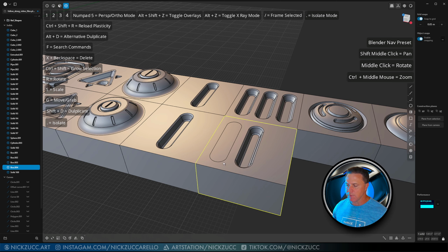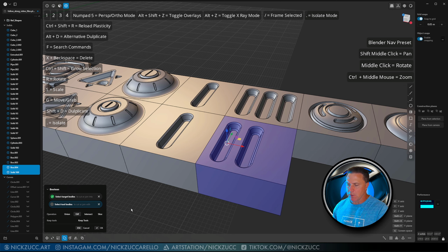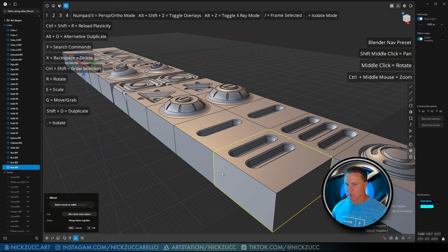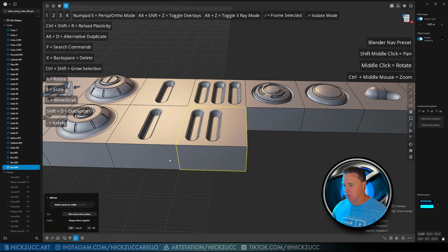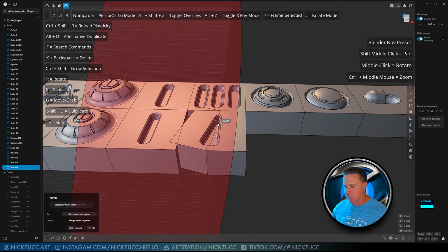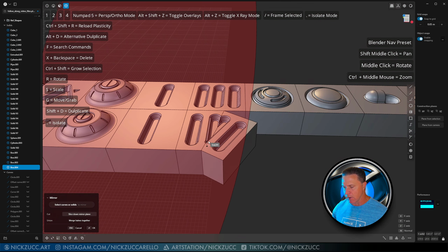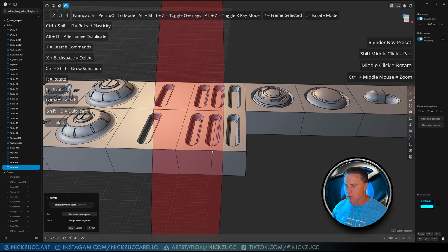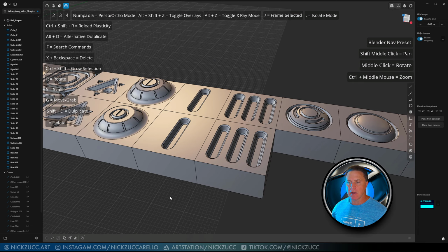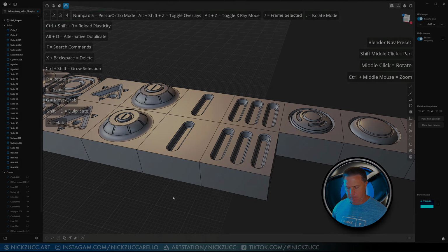Okay, so if I select this first, hold down Shift in object mode, tap Q, we can do a Boolean for that, right? And then I can just select the object, hit Alt X to mirror it. My center origin thing is way down there, so that's not going to work. So I'll just tap F to do a freestyle, and then I'll click in this center point, and then that'll give me the ability to start dragging this around and figuring out, well, where do you want to actually mirror it from? I'm going to do this here and do merge halves together, hit OK, and then we've made that shape, nice and easy.